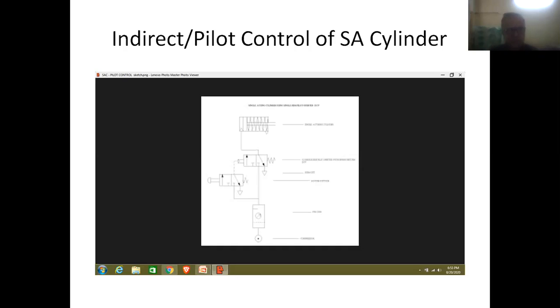And in the second phase of operation, the pilot valve comes to second position, and thereby it will be putting the DC valve in second position, and that is used for performing the return stroke of the piston. So, friends, this is the arrangement so far as control of the cylinder is concerned.